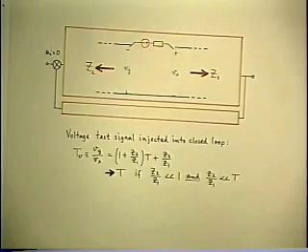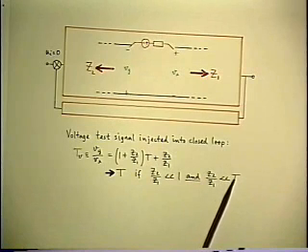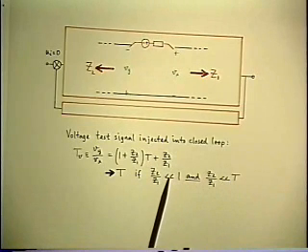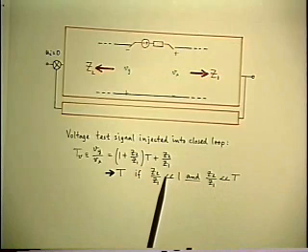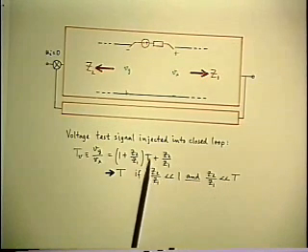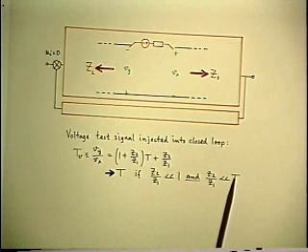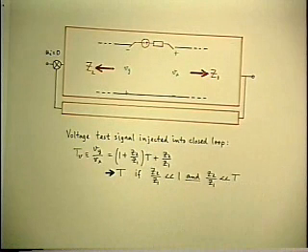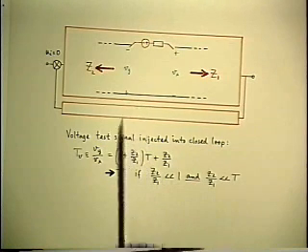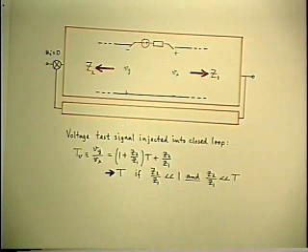At low frequencies, the loop gain is large, so the first inequality is the most stringent one. But when you're measuring loop gain beyond crossover, T now becomes less than 1, and the second inequality becomes the important one. So you have to worry about both of them at different parts of the frequency range.